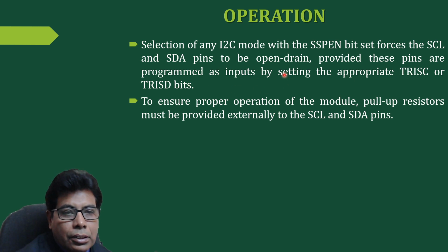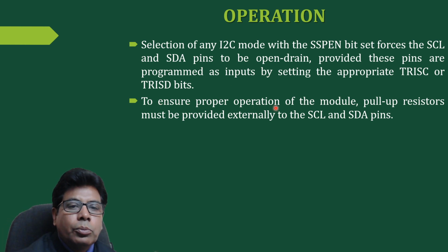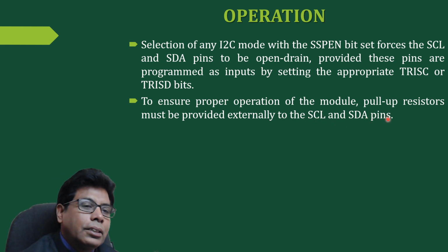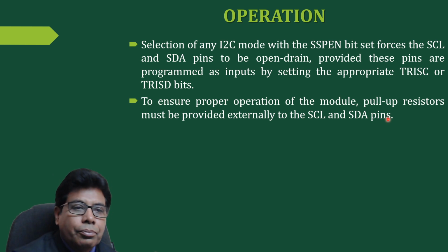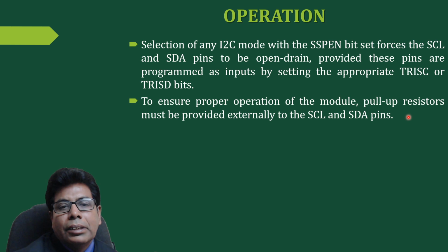We have discussed TRISB. To ensure proper operation of the module, pull-up resistors must be provided externally to the SCL and SDA pin. This is necessary, otherwise it will unnecessarily create problems. We had discussed this in the previous videos. So simply, we have discussed the different registers used in the MSSP I2C mode.